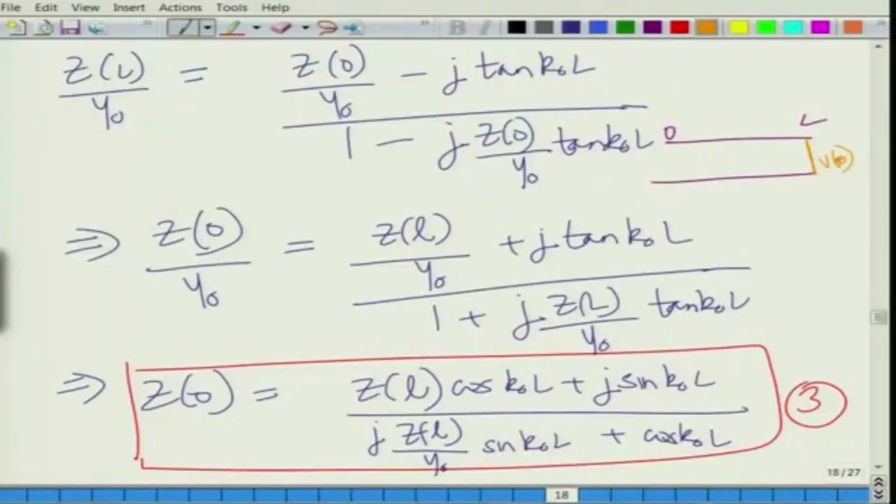It basically means that the velocity normal to the surface is 0, that is u n or u here is 0. So, when u is 0, what does it mean acoustically? It means P by u is z. So, if u is tending to 0, that means z is tending to infinity.